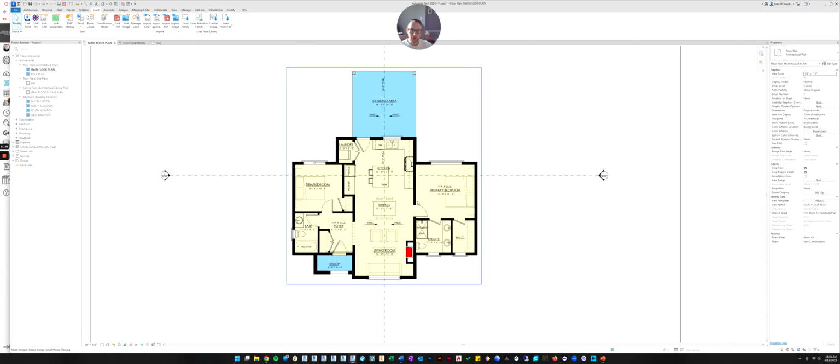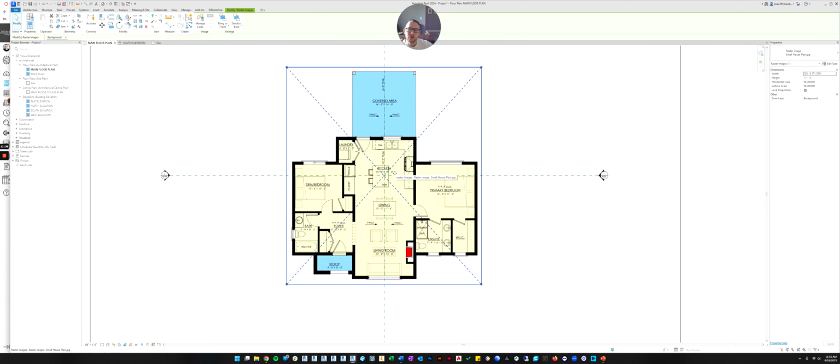if it did it right. So what you want to do is you click on the image, and we're going to learn a new command that you haven't learned before. It's called the resize command, or I think actually Revit calls it the scale command, but I remember it in my brain as resize because I think the shortcut is RE. So it's up here under your modify. So if you click the image, and then it automatically brings you to the modify image tab. Up here, there's a little white square with a bigger blue square, and this is the scale tool.